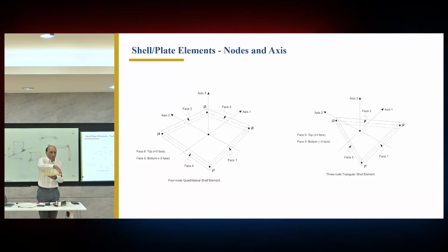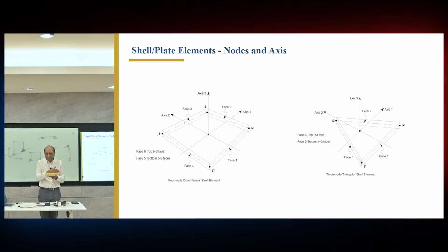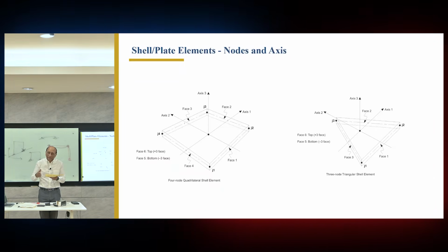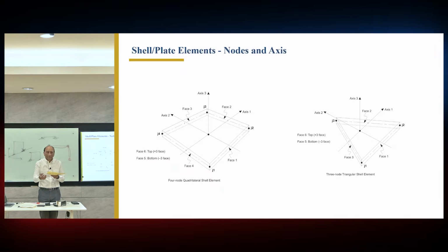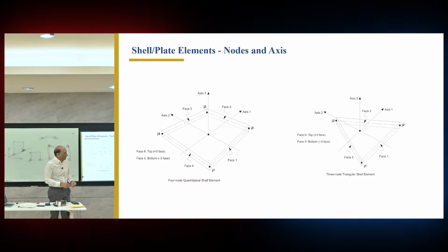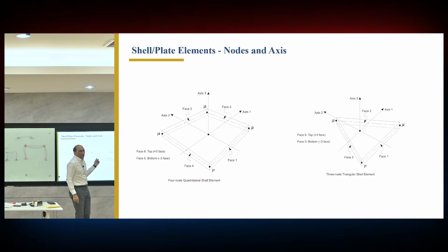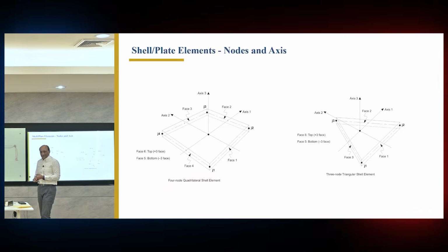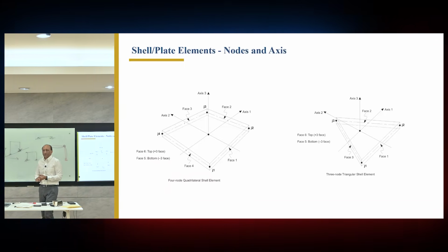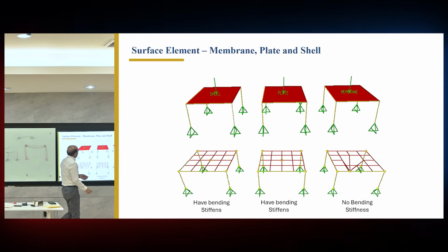Say this side we have soil, here we don't have soil. So you need to apply the forces and attach the springs very carefully. That's why understanding this diagram is critical for local axes, for faces, for applying load, and for checking stress.